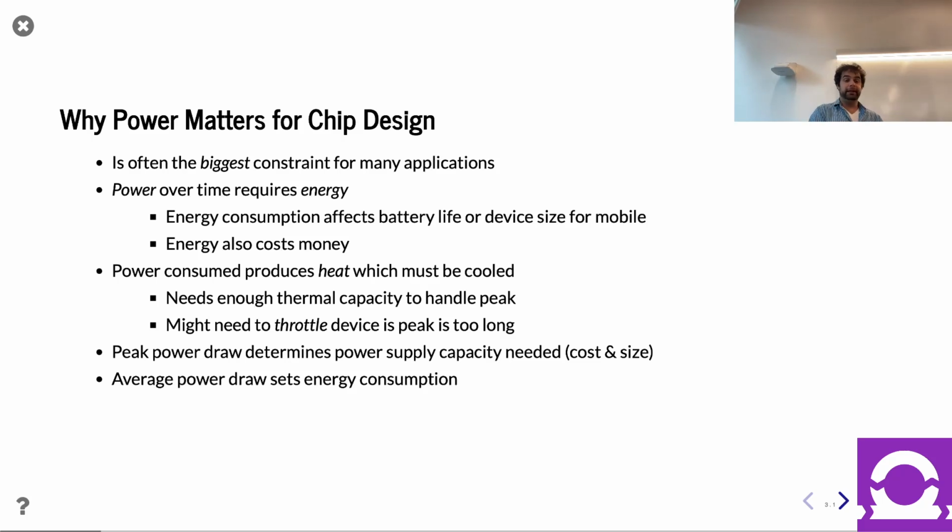Meanwhile, let's say you're building data center hardware, your power supply. When I say power supply, I don't just mean whatever's in your one box you're plugging the server into. I mean the entire process from going from utility scale power down to the appropriate voltages needed to actually power your server. There's often multiple conversions, multiple transformers, supplies, etc. Those are a lot of costs. And if you can control your peak power, you can reduce the cost of those. And so it's actually a large amount of cost spent to deliver a certain